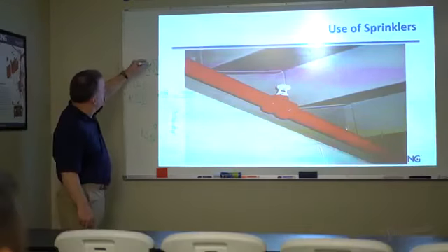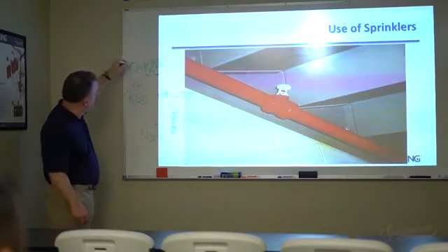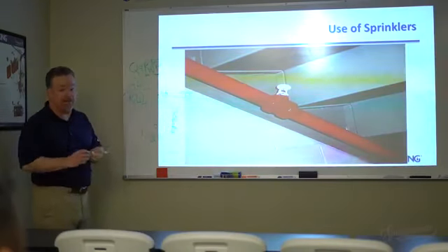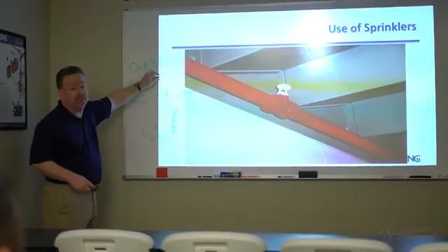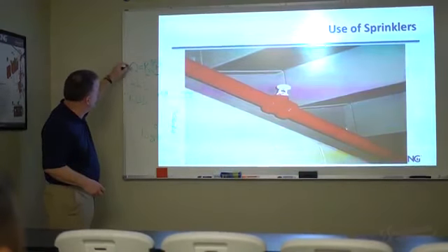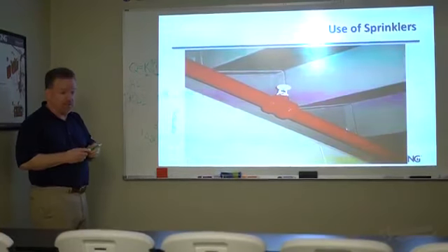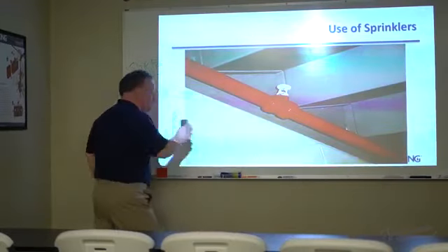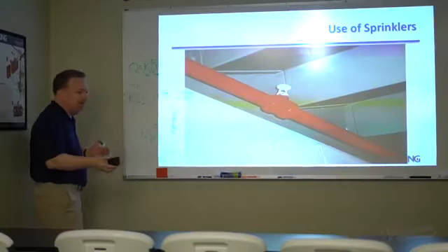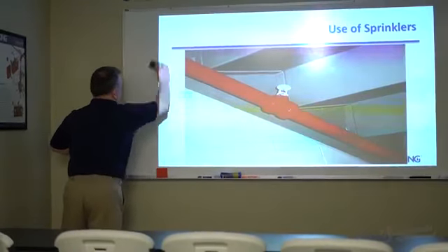So how much pressure can I flow through that K factor in order to get 20? It's going to be a higher pressure. The K factor is not going to change, so the pressure needs to change in order to get that coverage. Okay? So this is how sprinklers have developed over the years. We'll come back to that discussion.